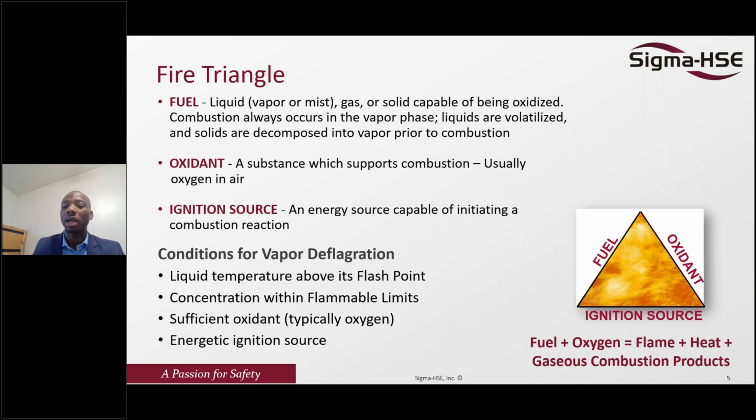So knowing this fire triangle, we need to understand, in case I have a solvent, how does this solvent ignite? There are some key parameters that we need to understand. First of all, we need to understand that with a pool of solvent, you apply heat or something like that, it's not just going to ignite. It needs to form a vapor at the surface of the solvent.